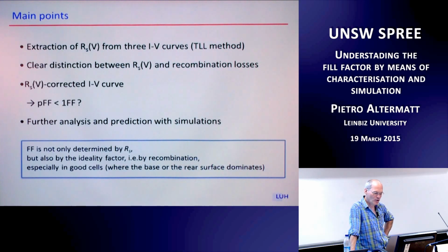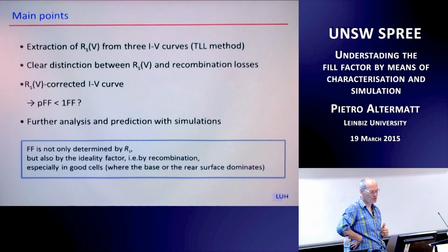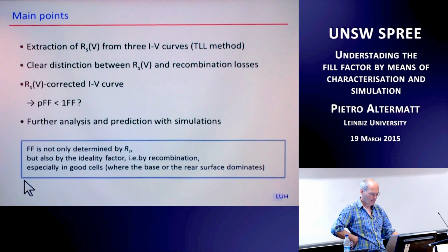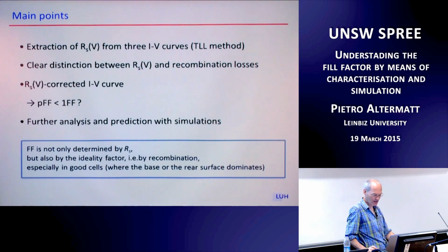And then when you work with these properly corrected IV curves, you can really do a proper detailed fill factor analysis and see what's the main reason for your low fill factors. And for further analysis or further predictions, I have found simulations very useful and really a task that's worth doing. And the fill factor is not only determined by RS, it's also determined by your recombination.